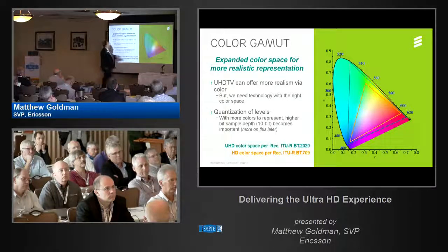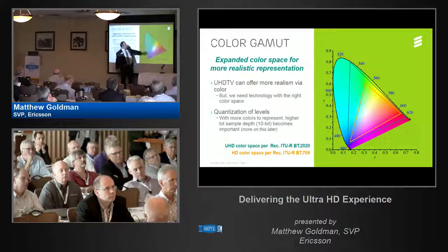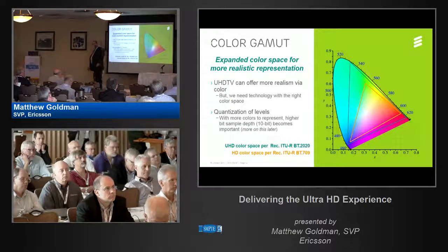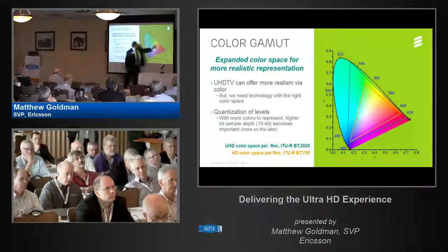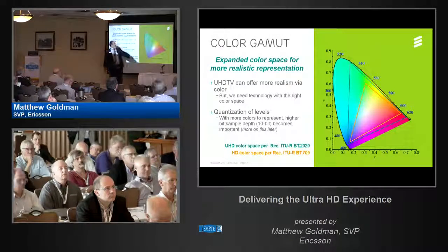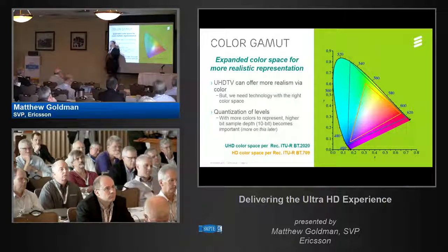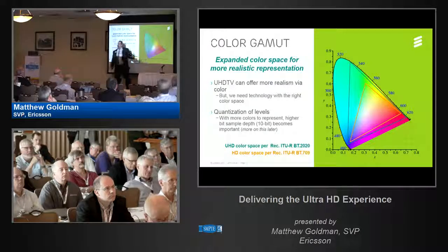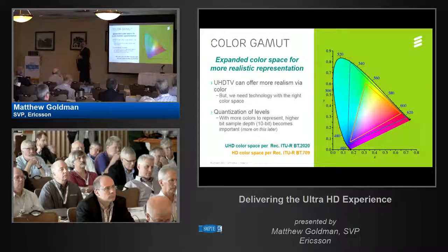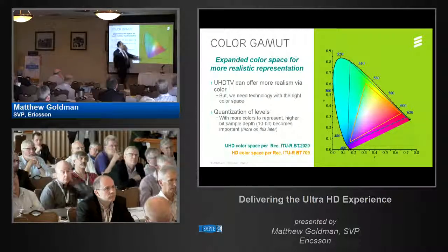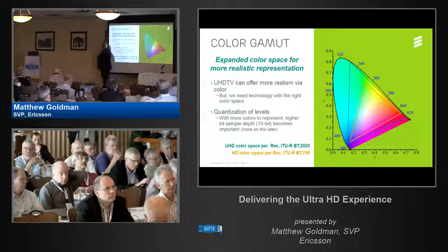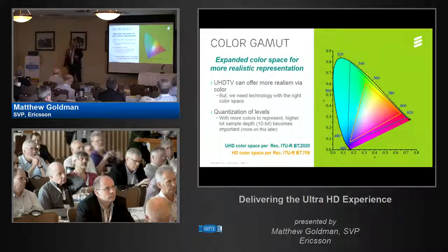In HD, this is a human visual colors, surface colors. In HD, all you see is this. That's known as ITU-R Recommendation 709. 601 was SD. Ever heard of 601? SD was actually smaller. The triangle's actually inside here. What does that mean? Well, none of this green is being seen. It still looks green, it's just muted. It doesn't look quite right. The green grass doesn't pop to you as how rich and beautiful green is. That red rose I was just telling you about won't be quite as red, and something that's deep blue won't be there. But it looks fine on TV because you're used to looking at TV, but it's not what it looks like in real life.